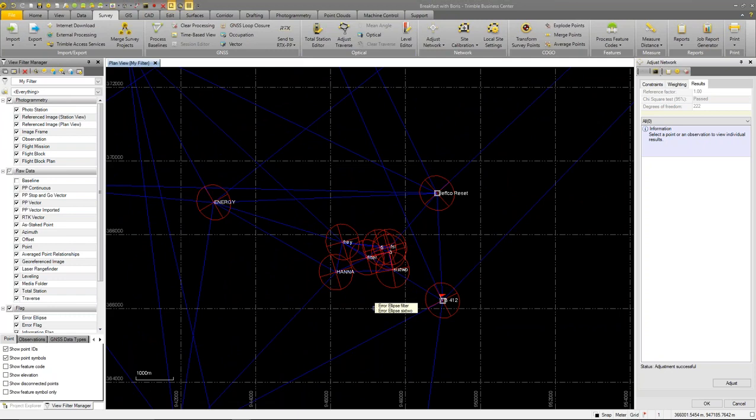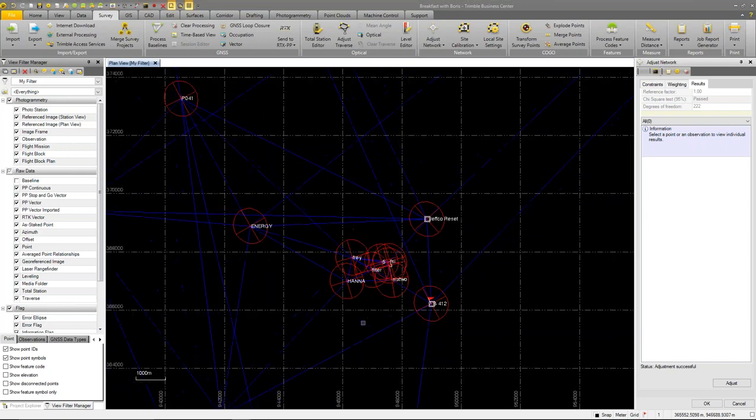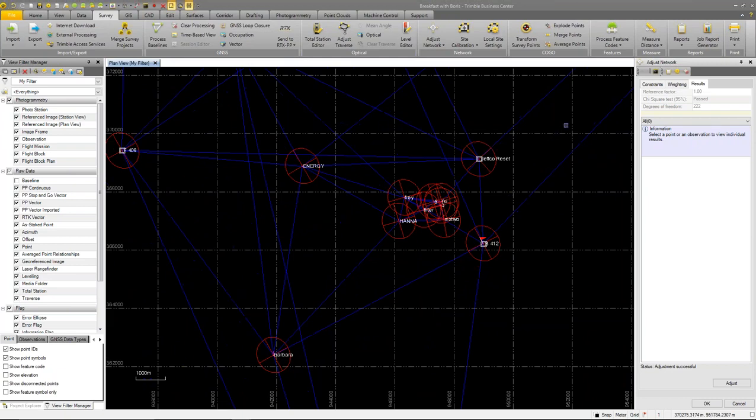Ellipsoid heights don't necessarily represent the gravity situation in the area and could actually provide a tilt in your vertical that does not indicate how water would run, for example. So I personally, for a lot of projects, would try to use elevations in the local area to make sure that everything is properly set up to match real construction conditions and the gravity there.